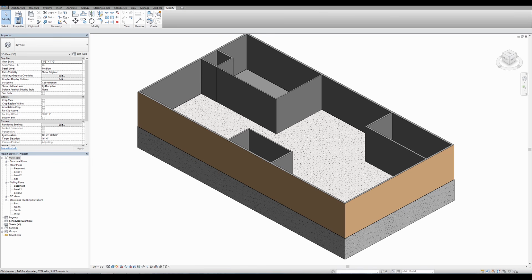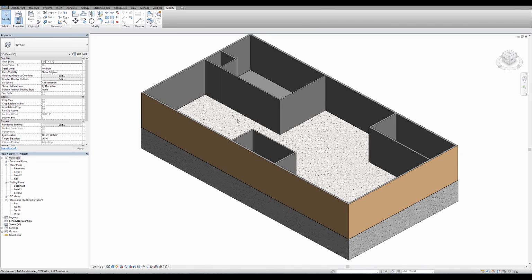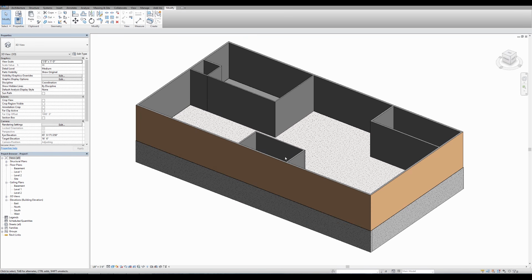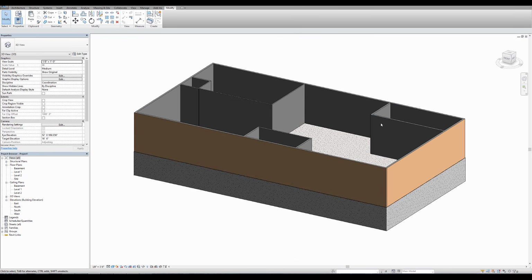Now there's a very good chance that you've created your structure in either an architectural template or a construction template. And because an HVAC system is a mechanical system, it is actually best created in a mechanical template. So what we're first going to do is go over to your structure or your building, copy it out of here, and then place it inside of a mechanical template. To do this, you need to head over to one of your elevations.